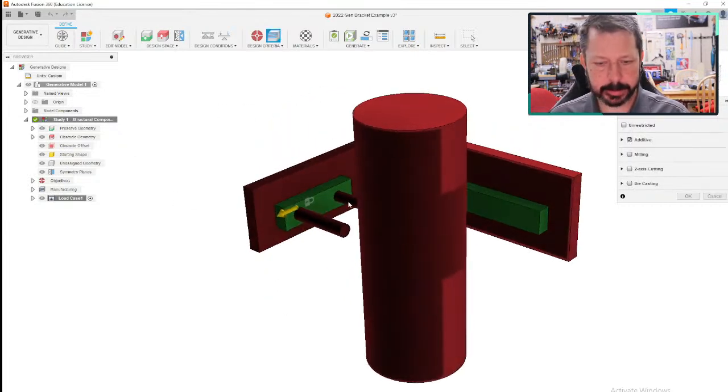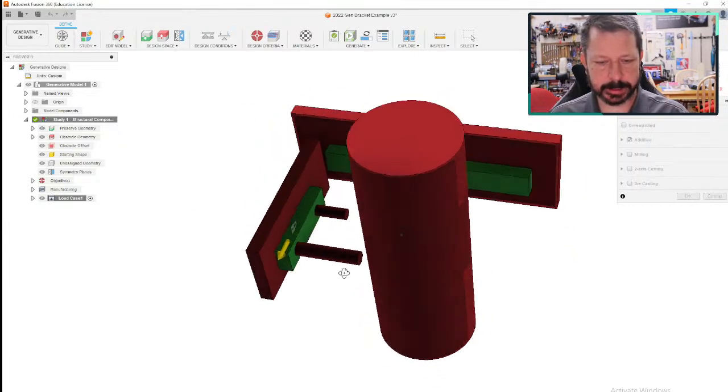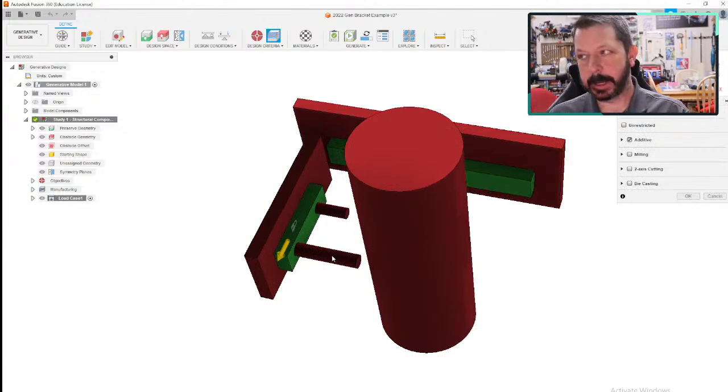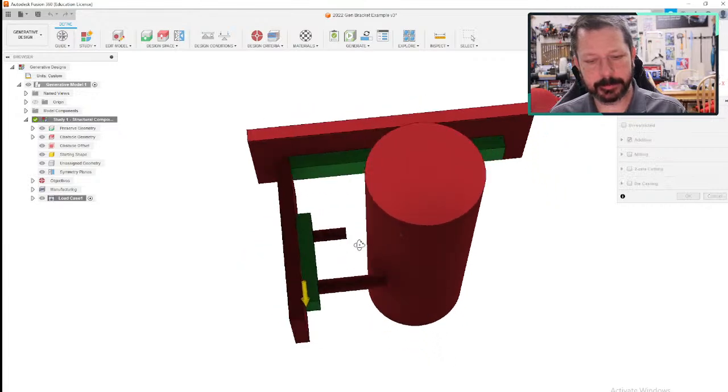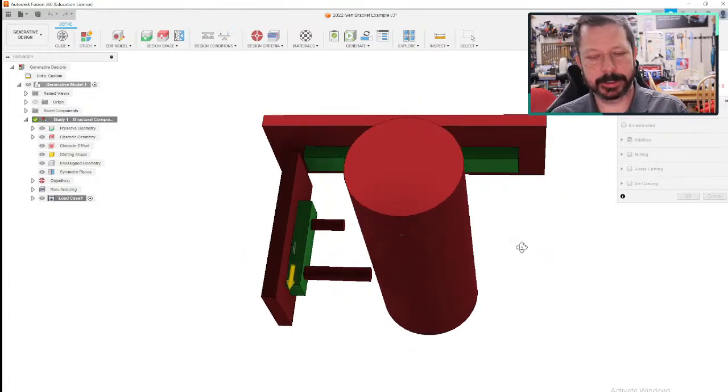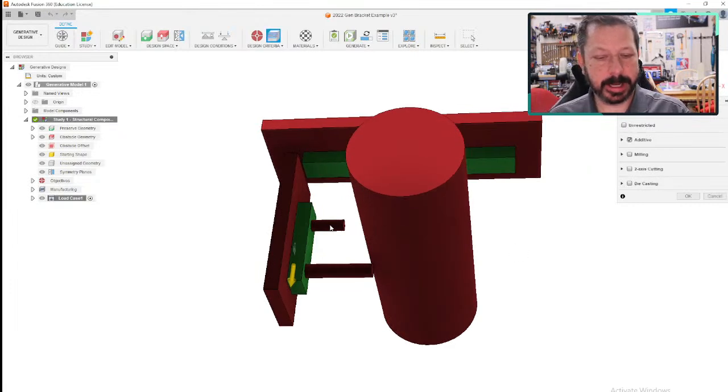I put these little cylinders, the little ones, kind of in the middle here, to keep it from growing any material there, and I probably should have moved them all the way out. I don't remember what the solutions looked like, but the idea was that I've got to put a screw in here to screw it to the wall, so I need a way for the screwdriver to get in there and reach the screw. Thinking about it now, these probably needed to go way out here so they didn't put any geometry in the path of them.